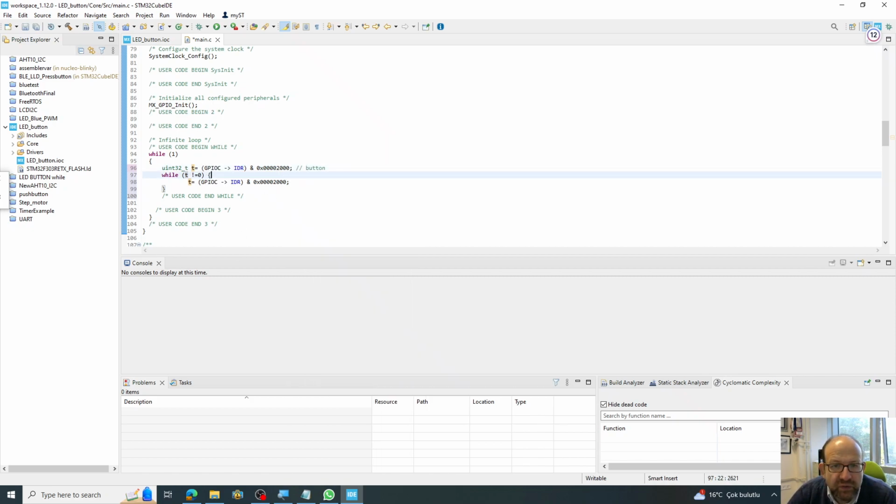That 1 over there in 2 represents the 13th bit. So I can mask that out and look at that value. If it's equal to 1 or any value other than 0, then I need to stay in the loop, as long as that value is equal to 1 or any value different than 0.